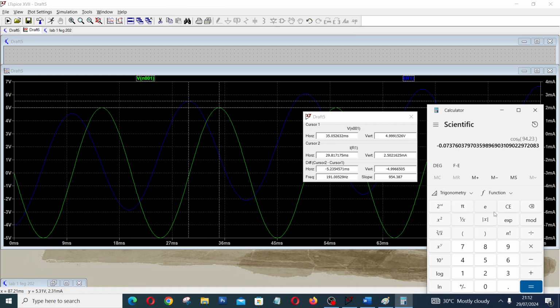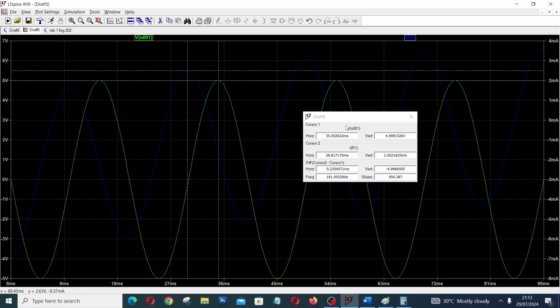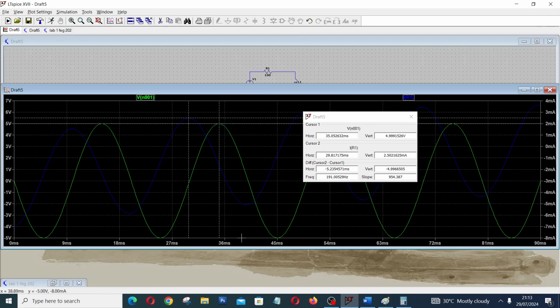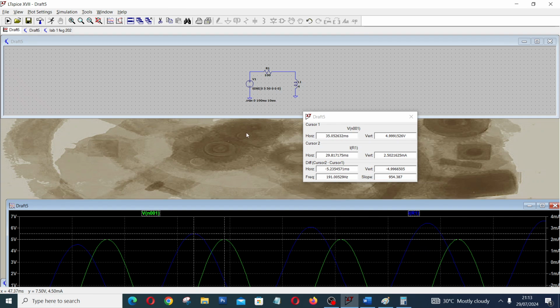The implication of this very poor value is that virtually all the power generated by this system will be wasted in the coil of the inductor. That is the implication, because we are saying that no power is actually being used by the load. That's why you are getting a value as poor as 0.07. So now you have seen the power factor is very low.